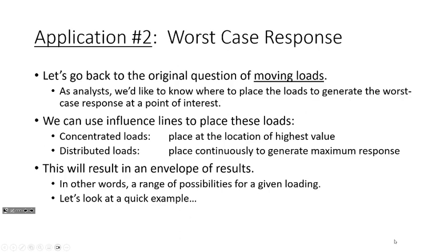I mean, as analysts, we need to know where to do that, and we need to know that response for one very simple reason. We need to be able to design, okay? If you're designing a bridge, let's give you the bare basics of design. Whenever you're designing, there are two sides of the equation. There's the loads and there's the resistances. The loads are what we're talking about in this course, which is all the structural analysis, all the shear diagrams, the moment diagrams necessary in order to determine the loads that we need to design for. And the resistance is how strong the element actually is. And as long as the resistances are greater than or equal to the loads, the beam is safe, or the structure is safe. That's structural analysis or structural engineering in a nutshell.